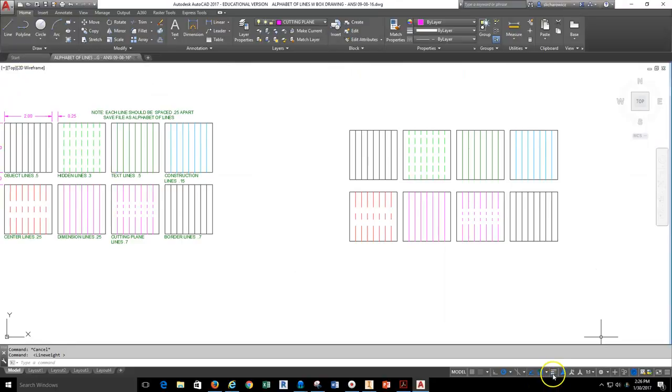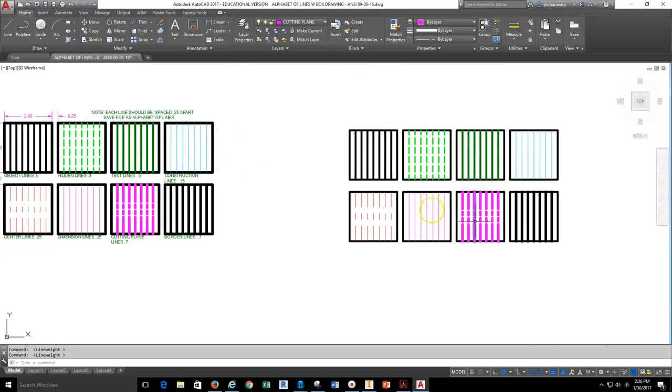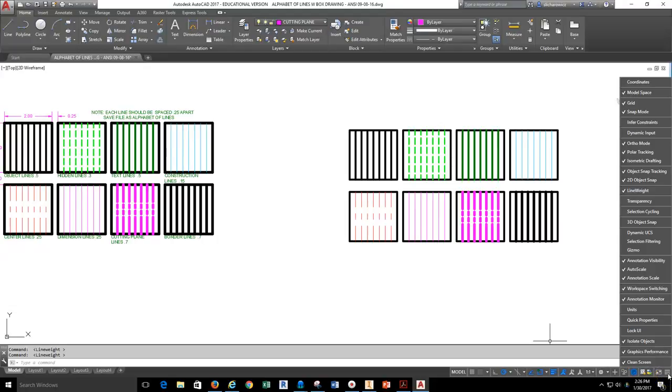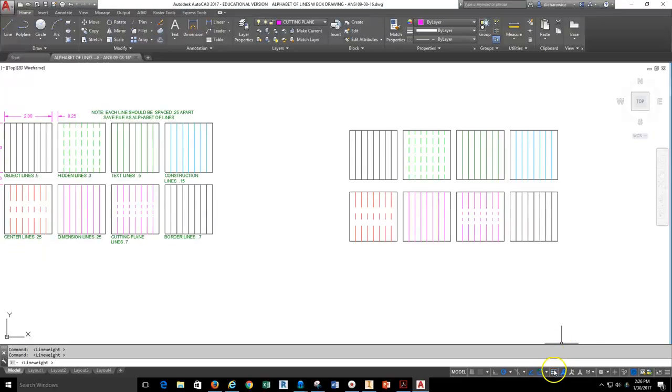Being able to turn on line weights to ensure that you are on the proper layer is important. If you do not have Show Hide Line Weight as an option on your drafting tools at the bottom, additional tools can be found in the 3 line tab at the bottom of the drafting tools by selecting it and then selecting the necessary tool. Make sure line weight has a check in it, and then you should be able to select and deselect show hide line weights.